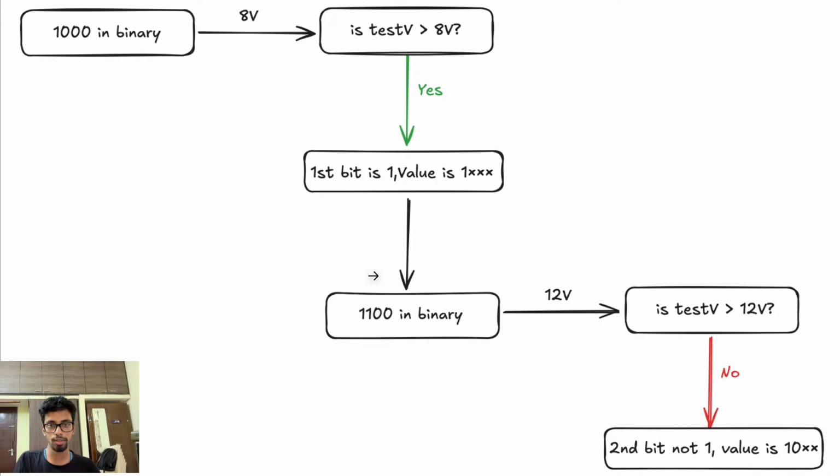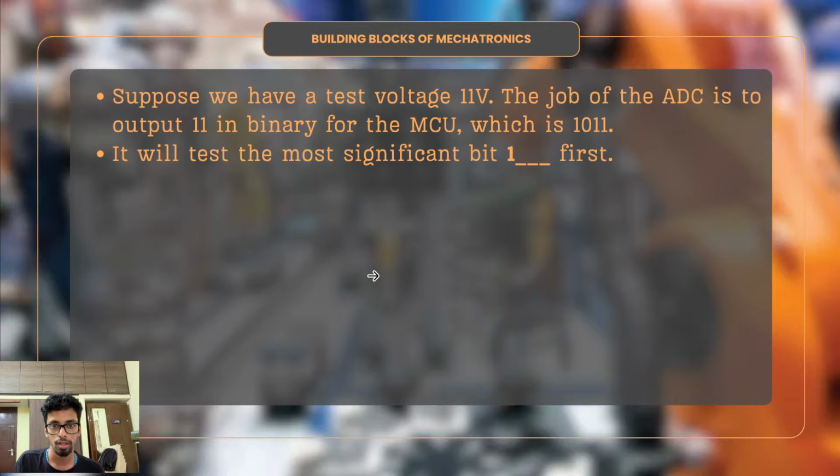So you see, as you go back along this flow chart, even though it might have been a bit hard to understand at first, basically it read a voltage between 0 to 15 volts in exactly 4 steps. At maximum, an ADC needs only 4 steps to read any voltage, provided it's an integer voltage. I cannot guarantee the same thing for 2.5 volts. You know what, for an assignment we can keep that.